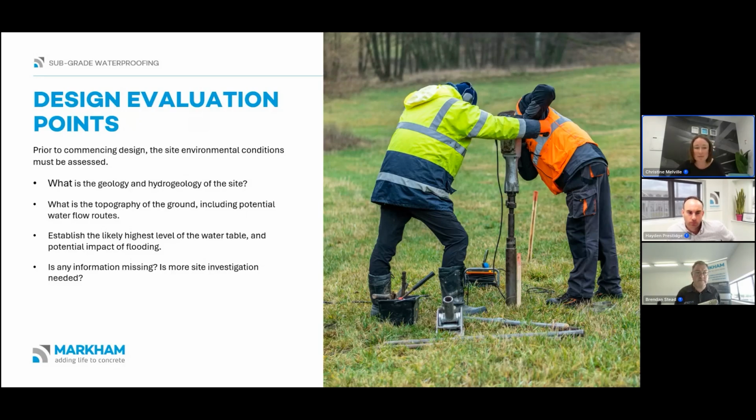Where's the water table? But as Hayden's touched on as well, BS 8102 2022 is about establishing where the water table could be. So taking into account structures being built next door, what's the highest possible level the water table could get to, and where are the flow routes for a major weather event.